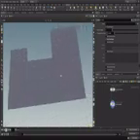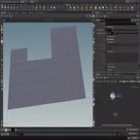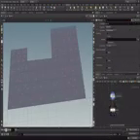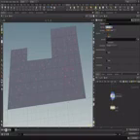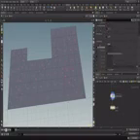The only thing I don't like are these, well, the remainders of our divide node. So we're going to be removing them. First, place down a group node, and with this group node, we can set it to edges, and we can select it to include by edges, and then do something like unshared edges.